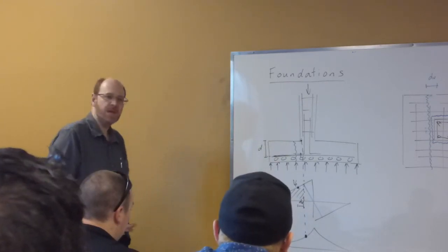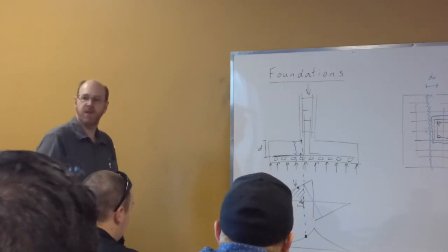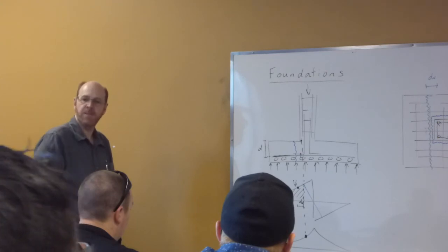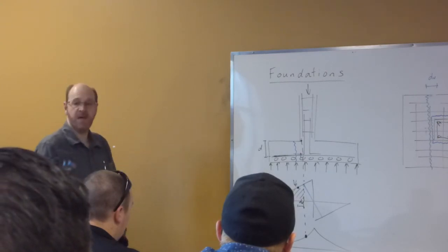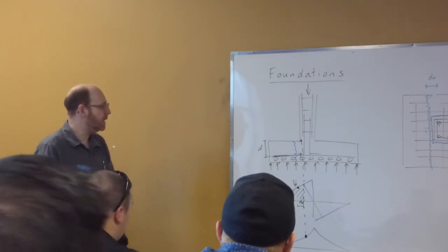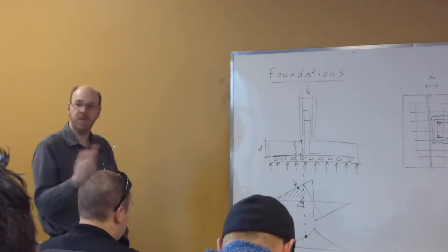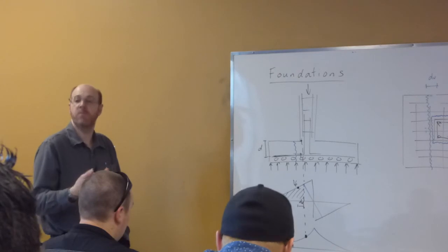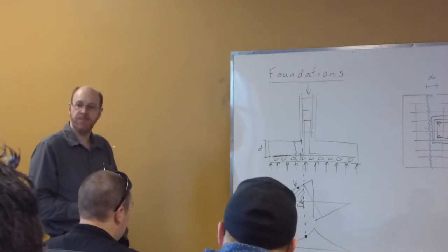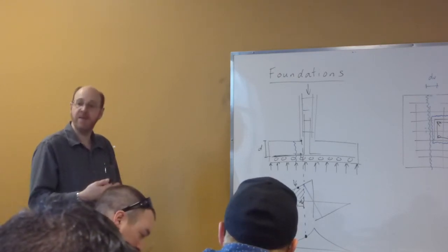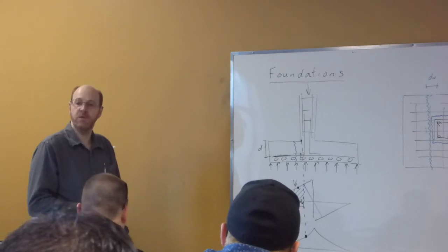So if you've got a significant amount of moment there, then that's something you might want to add in as well. And of course, if you've got a rectangular footing, what you end up doing is designing in two different directions separately. So you'll have a north-south direction and an east-west direction with two different moments potentially, and design configurations in the two directions separately.